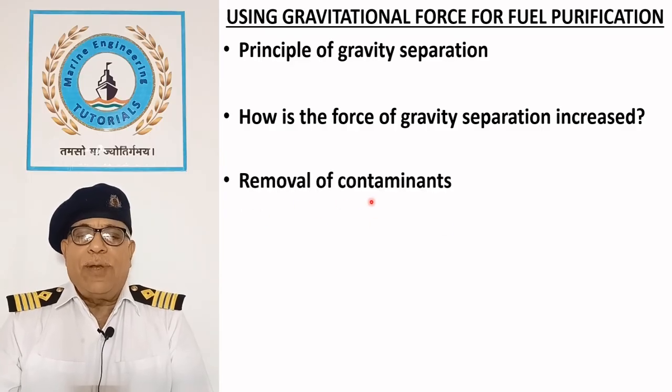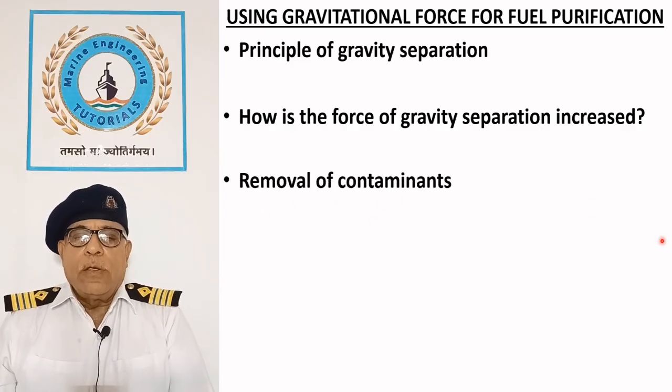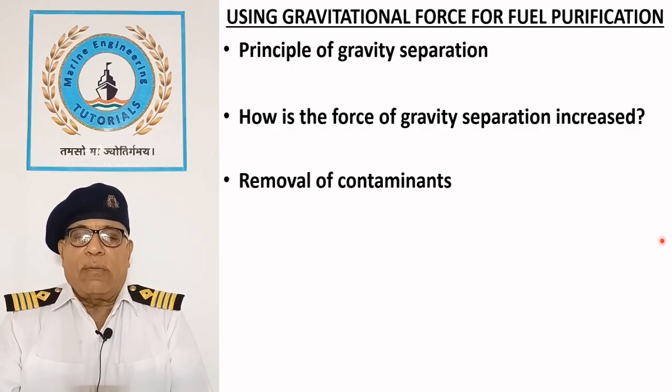Removal of contaminants. Separated water is frequently removed from the drain valve. Heavy contaminants settle at the bottom, which are removed during the survey of the settling tank at 5 yearly intervals.